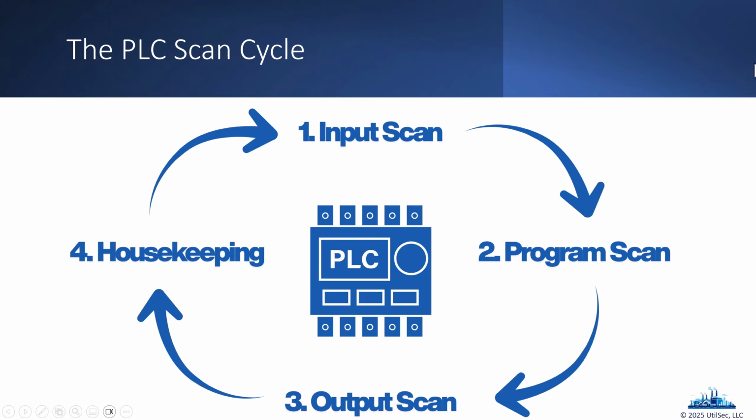Now, we didn't get into too great of detail when we talked about the PLC scan cycle previously, but we saw this. Remember, we start off with the input scan, right? Meaning we bring in the data from our inputs, the data we have for the sensors. If we go back to the thermostat example, we're continually, let's say every second, bringing in the value of the temperature that's read in the room. We're bringing that into the controller. So we bring in the data through the inputs.